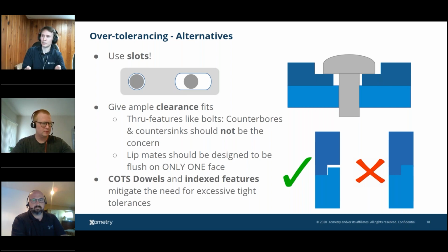We use coordinate measuring machines for profile tolerances, for example, to measure those surfaces or those lines, and that'll instantly add hundreds of dollars and a few days lead time to a part, but you're going to get the accurate measurement that you're looking for on that call out. So just understand that you can constrain a lot of stuff, and definitely don't do a surface profile on the entire part of 0.006.